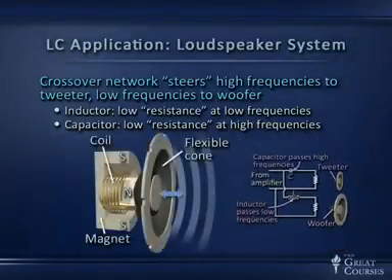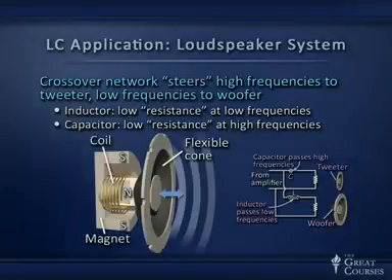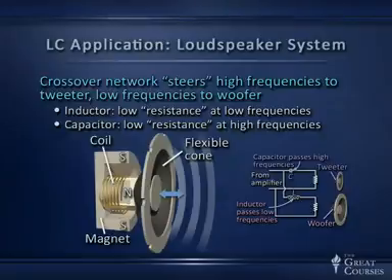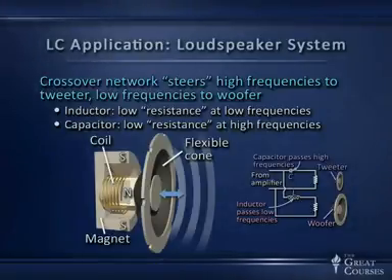And on the left, you see how both these speakers work. They involve a coil wound around and attached to a moving flexible cone. The coil is around a magnet but not attached to it, and the coil moves back and forth with magnetic forces as audio frequency currents run through it. So there's an application of this idea.